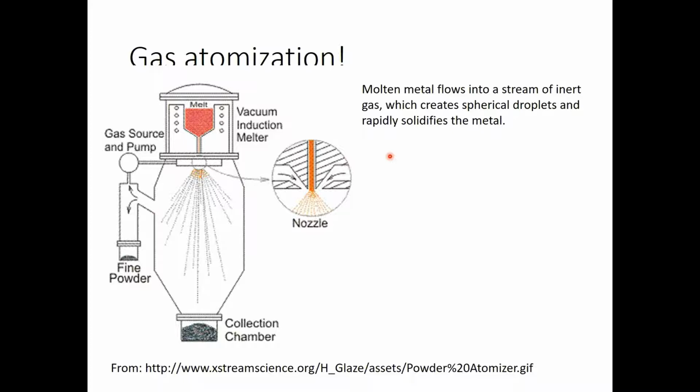You have to use inert gases. Argon and nitrogen in the N2 form are two common inert gases to make these metal powders. Nitrogen sometimes gives problems, particularly when you're dealing with stainless steels, because nitrogen thermodynamically stabilizes austenite. So there's several research articles and literature with retained austenite and using nitrogen. Before you get too excited about nitrogen, though, we're going to do a problem related to argon, where argon is essentially used as a coolant to help create these spherical droplets from a metal stream.